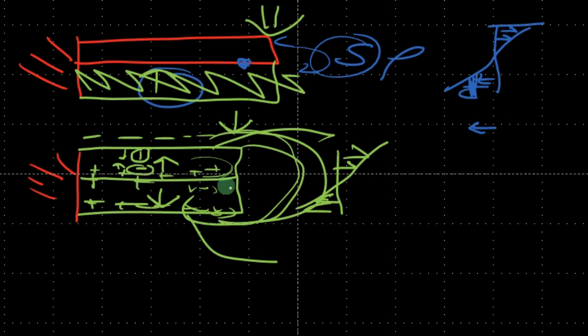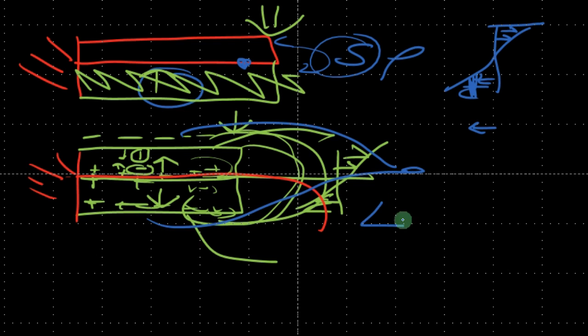And if you hook these two up and take this out, so basically you have a wire coming out from here, and you have another wire from here. These two, you'll generate a delta V between these two electrodes if you orient them separately based on their compressive and decompressive stresses and strains, because you don't want them to cancel. So this is a unimorph here and a bimorph here. The key thing is you want some type of non-symmetry in order to develop a net stress in the piezo element. So now we'll go on to the question posed.